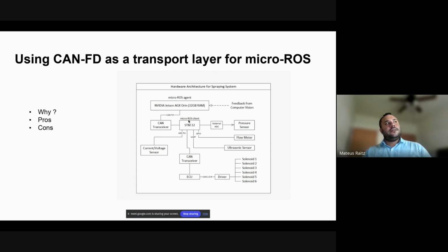So sometimes you might need to create your own custom message, and on your ROS side have another node that converts that back into a standard ROS2 sensor message or whatever type of message you're using. If the messages you are trying to send are too big, you might need to break up some of those.